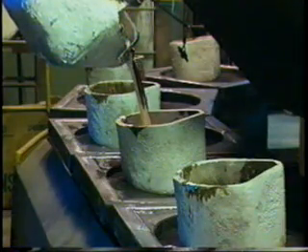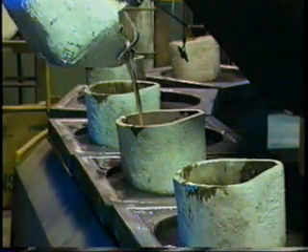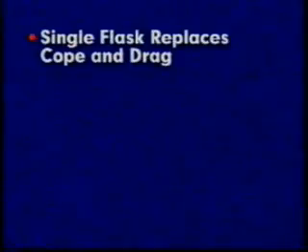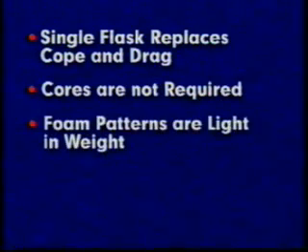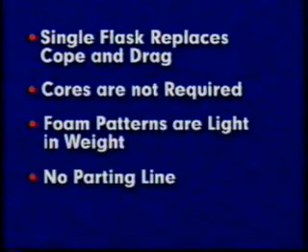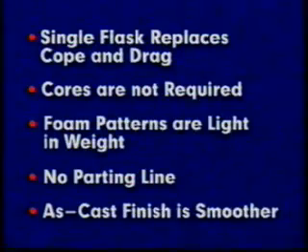Evaporative foam casting has several advantages over conventional sand casting. These advantages include: a single flask replaces the cope and drag. Cores are not required. Polystyrene foam patterns are light in weight. There is no parting line, and the as-cast finish is smoother.